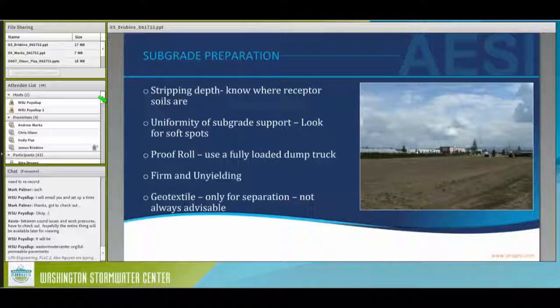As both a foundation engineer and an infiltration design engineer, again, I'm caught in the eternal tug of war when it comes to subgrades. For pavement support, you want as dense a subgrade as you can possibly get. So you encourage compaction to 95% of modified Proctor. You want an absolutely bomber subgrade to support the overlying pavement.